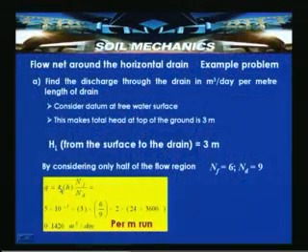So by substituting now these values, K is the coefficient of permeability and H is the head loss, with the number of flow channels and the number of potential drops, and multiplied by 2 because we have two flow regions along this longitudinal drain. So multiplied by 2, which gives us 0.1426 meter cube per day per meter run of the pipe. This is the rate of seepage or rate of discharge which can occur per meter run of the pipe. So by using this concept of flow net construction, simple problems like the drain problem, which we treat as a two-dimensional problem, can be solved.